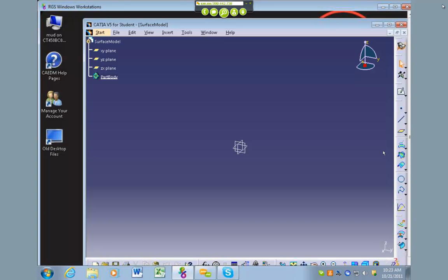Okay. So depending on the orientation of your car, your surface model is going to pop in. So you want to make sure, first and foremost, that you're sketching on the right plane. Like if your chassis is on the XY plane and it's moving along like this, you want to make sure your surface model is on that same orientation. I would hate for you guys to create a surface model, try to bring it into your skeleton, and have it be sideways or upside down. That's a lot of work, and for top-down modeling, the orientation of the planes is important.